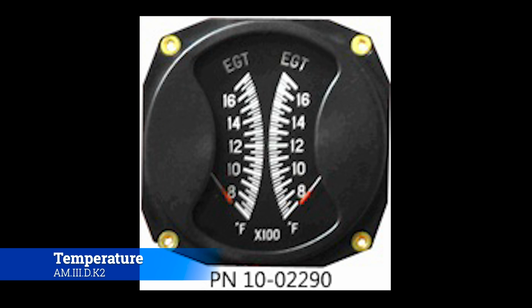If it's super duper hot, then there's probably a reason it's really hot. The mixture's not set right. The valve isn't working correctly. The metal is getting too thin, or whatever the thing is. But the point is that it really points us to, hey, look, there's something not right here. If it's super low, then we know we have insufficient combustion of some variety or for some reason.